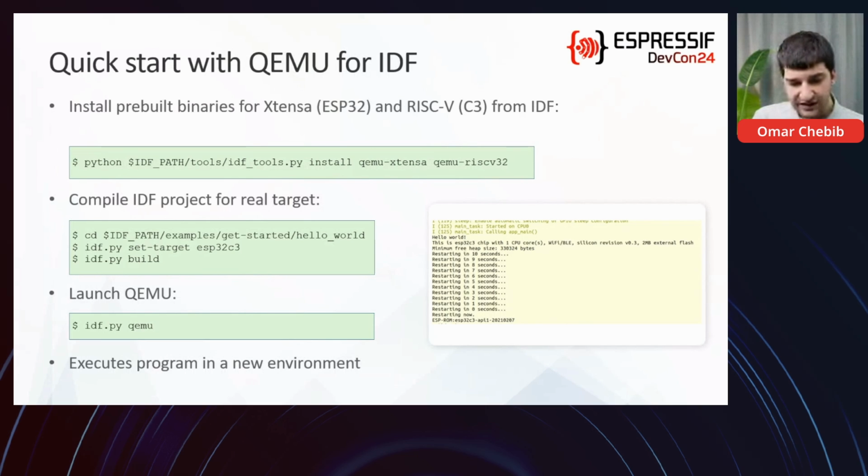And this will be executed in a new environment, so a new flash with new eFuses. So if in your application you burn eFuses, you can just exit and then rerun idf.py qemu, and you will have new eFuses, and you can try again.